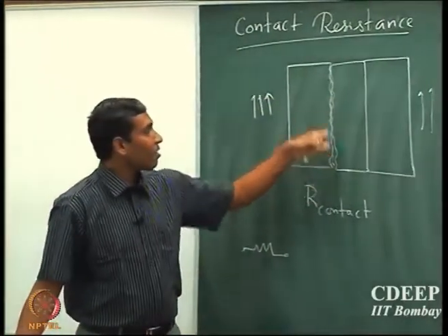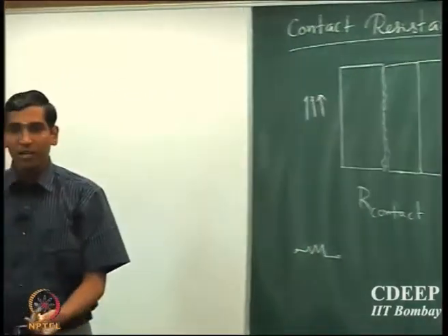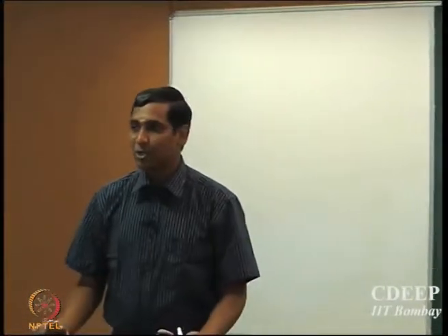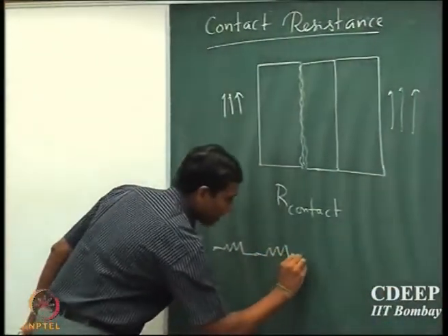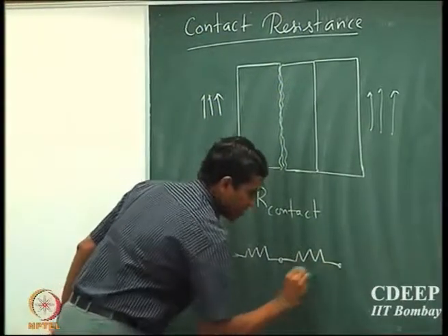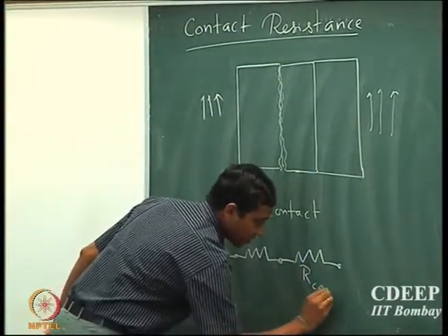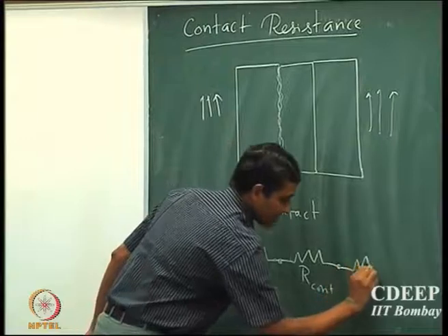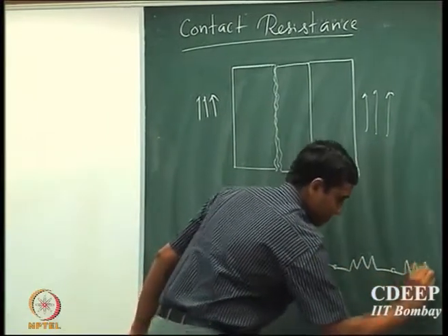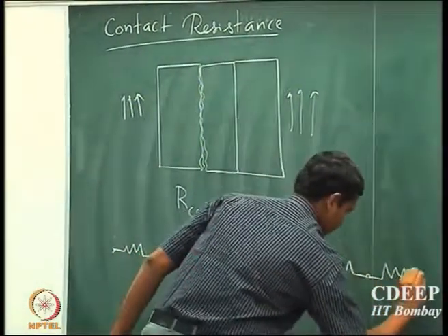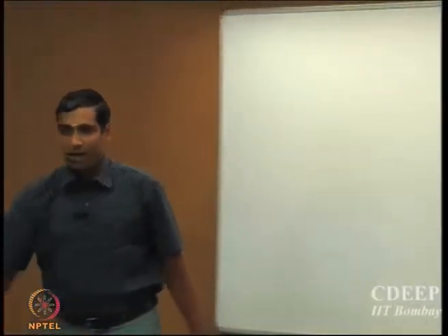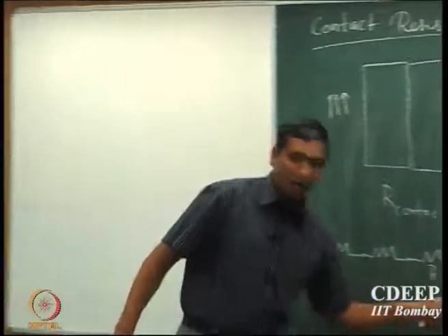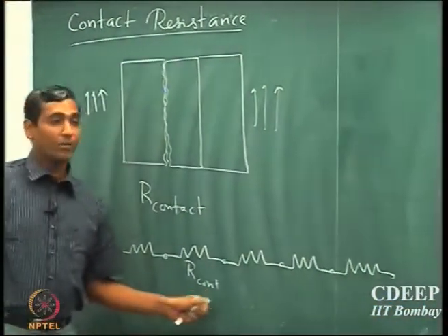But because the contact position is not smooth, it is going to offer a certain resistance to heat transport, and therefore you will have an additional network which is the contact resistance, which will come in series. The other 5 are the same as what we saw a short while ago. So we need to include a contact resistance which is present in between.